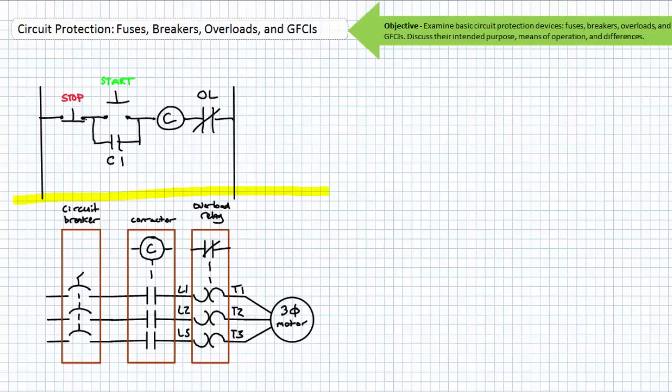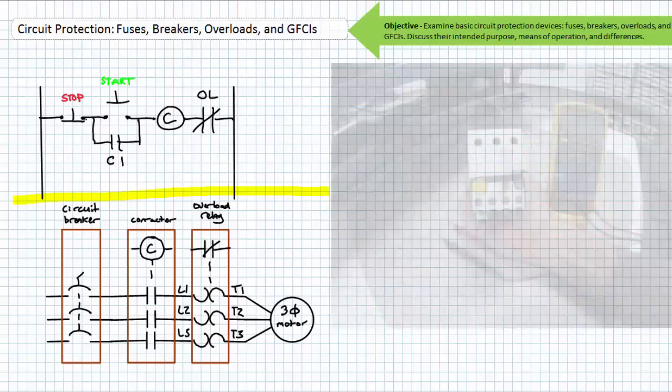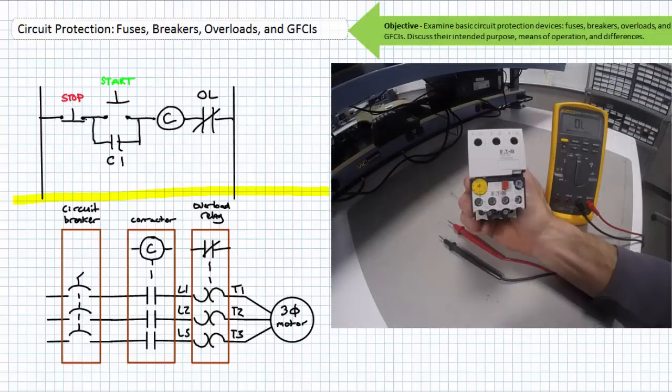Today's takeaway point about overload relays is this: they are sensory devices only, they do not break the circuit in the event of sustained overload conditions. They simply tell another device to do so. Here's a three-phase overload relay. It has three paired overload elements and two auxiliary contacts. The 95 to 96 pair is normally closed. This relay has an adjustable overload setting, quite like our motor starter.